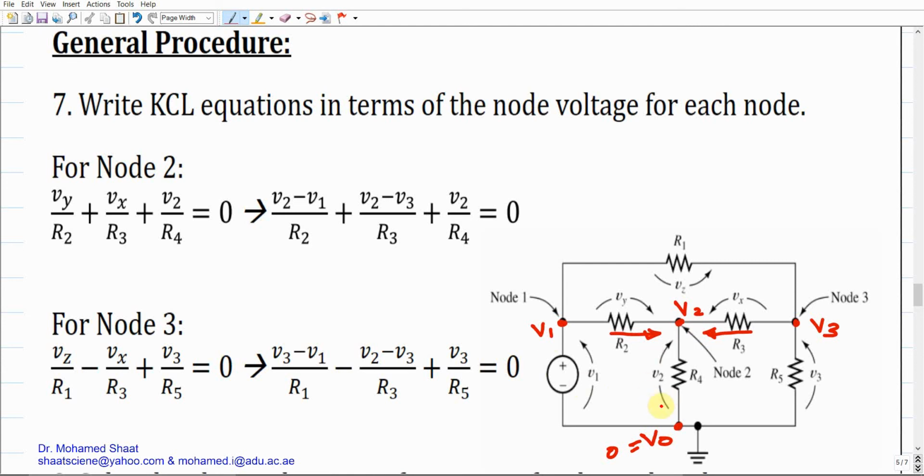The same thing for this element voltage, which is V2, we have a current that goes also to the same node. As you can see, this node is an intersection of 3 electrical elements. So the Kirchhoff current law for this node will depend on 3 currents. Why 3 currents? Because it is an intersection of 3 elements, and each element has its own current. Makes sense? So we have 3 currents and all of them are entering the node. If we sum all of them, the right side should be 0. This is the Kirchhoff current law for this node, which is very simple.